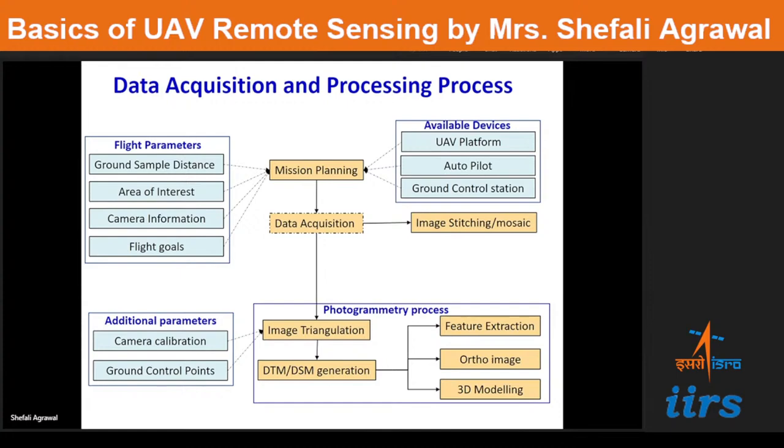And it is also important to consider the wind speed when selecting these sites, because the UAV needs to take off and land against the wind. And this enables it to fly more stable in low speed stages. So wind speed plays a very significant role. So it needs to be specified. And providing this information will enable a better estimation of the time required to fly an area, because it's easier to control, right?